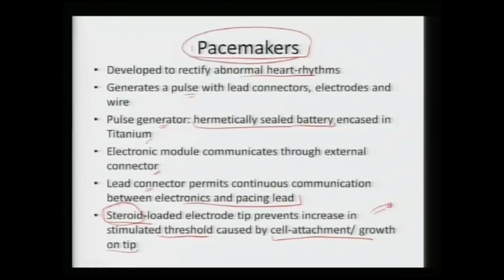So, we can see the pacemakers are utilized for rectifying abnormal heart rhythms. The heart needs to have a particular rhythm to keep beating. So, it generates a pulse at a particular frequency, which is connected with lead connectors, electrodes and wire, and that pulse generator is sealed. It is sealed and encased in a titanium alloy. Again, the electronic module communicates through an external connector, which basically permits continuous communication between the electronics and the pacing lead while providing fluidic sealing to it.